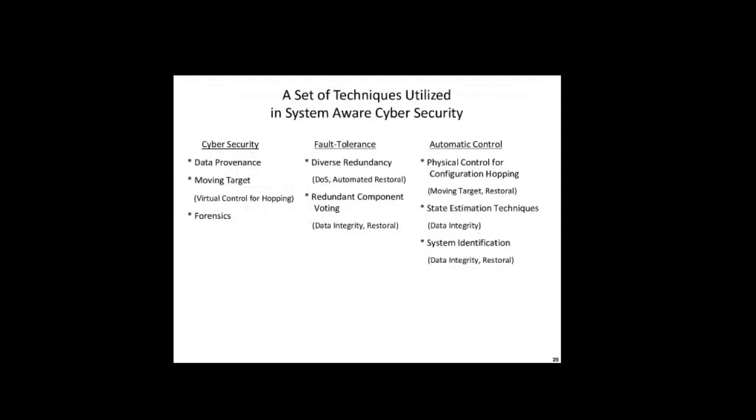Okay, let me talk about the techniques for design. Cybersecurity provides ideas like data provenance: does the data come from where it's supposed to? So I can monitor that. What we've done for defending our Sentinel is not only have diverse redundancy, but we can dynamically hop which configuration is dealing with monitoring and reconfiguration, changing every 2 seconds which one is managing that, so that an attacker would have to create attacks that crossed the diverse set of designs as well and do it every couple of seconds.